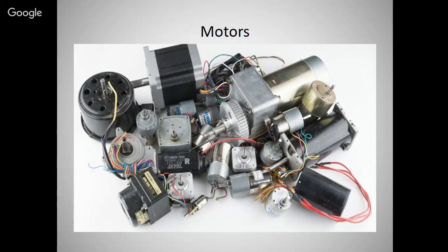These are the motors. You can use a servo motor. I made a 6 degree of freedom robotic arm, servo motor based, in my MTech thesis. You can use the servo motor also, but with a servo motor the programming part increases. With a DC motor there is less programming. It also depends on whether you want precise movement in the robotic arm for pick and place. If you want very precise movement, you can use a servo motor or a stepper motor, like in a printer or a CD drive, where a stepper motor is used. Here I have used the DC motor.